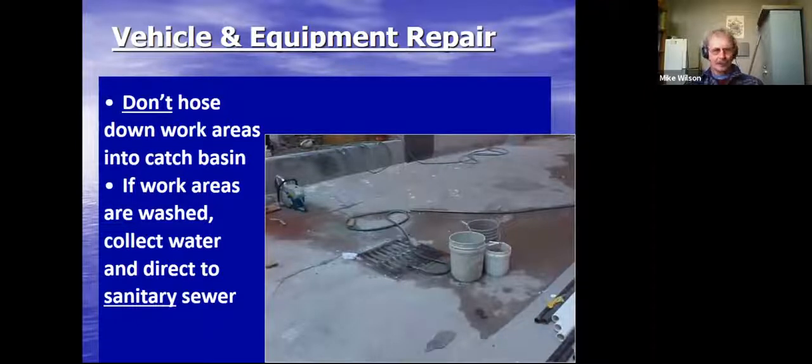Don't hose down work areas into the catch basins after you're finished when you go to clean up. If those work areas are washed, collect the water and direct it to the sanitary sewer. Washing it down the drain does not make it disappear. What it does is make it go into our local waterways and again pollute our local waterways.